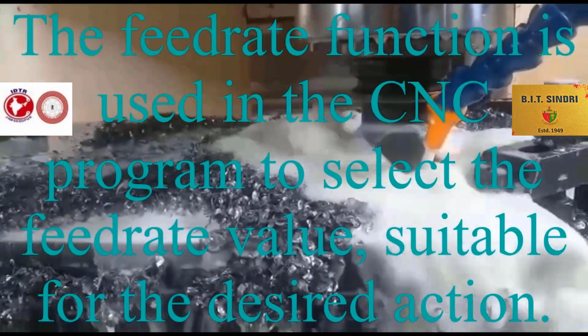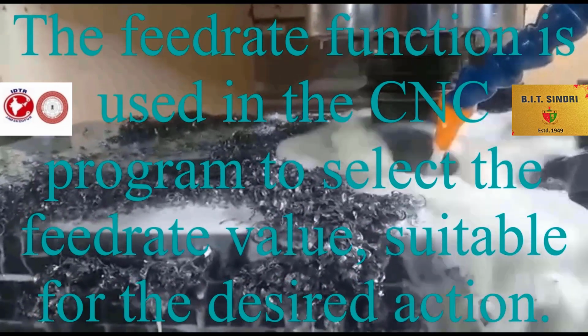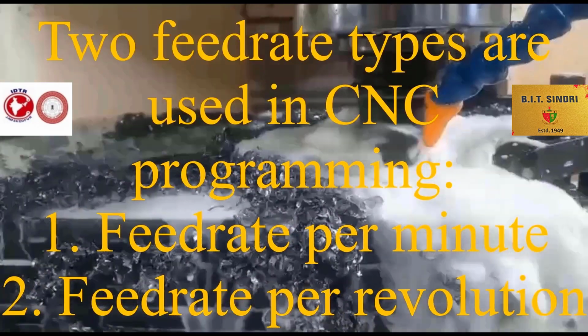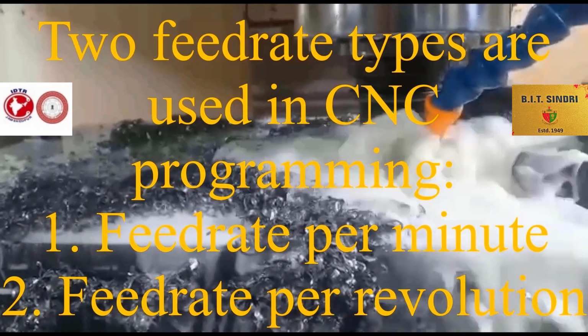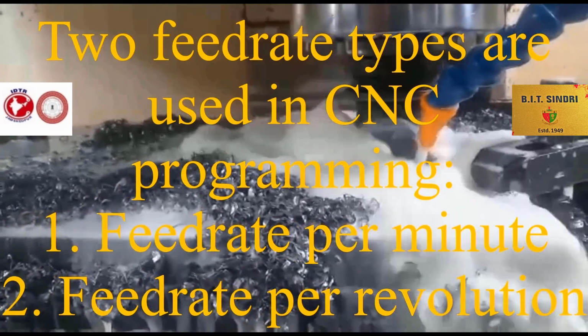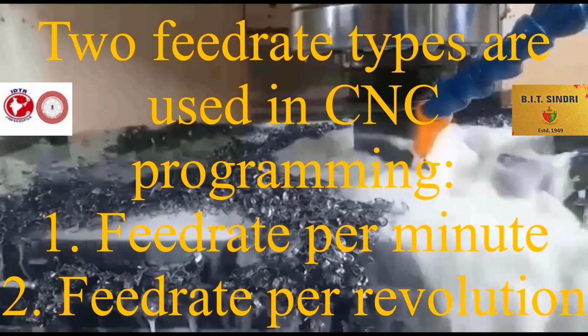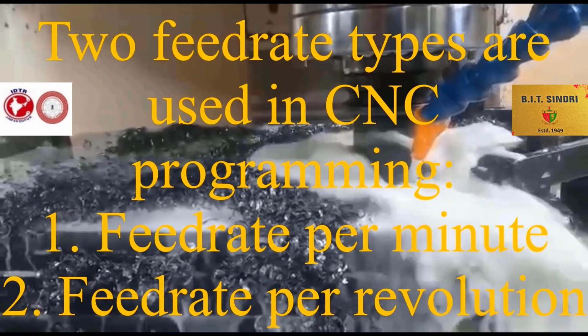The feed rate function is used in the CNC program to select the feed rate value suitable for the desired action. Two feed rate types are used in CNC programming. The first is feed rate per minute and the second is feed rate per revolution. The most common types of machines, CNC machining center and lathe, can be programmed in either feed rate mode.